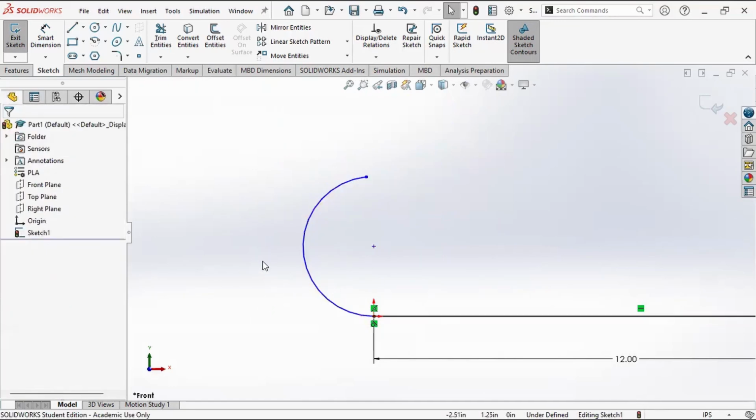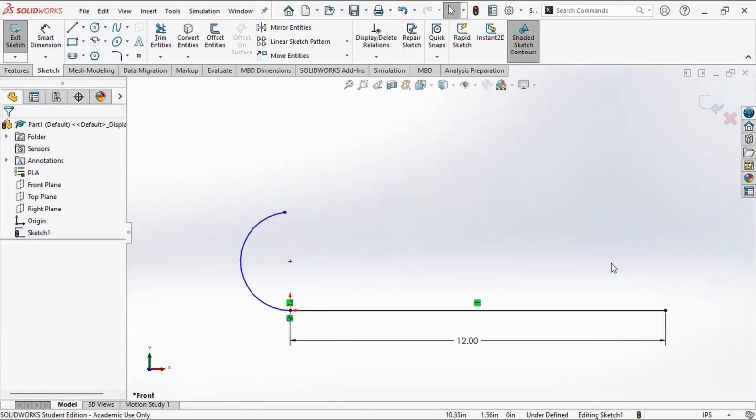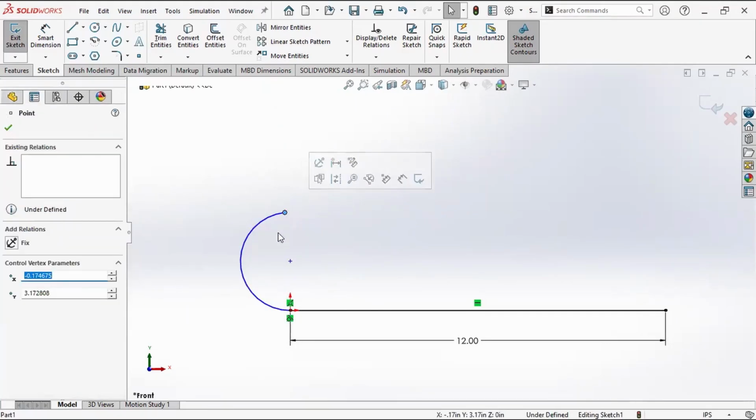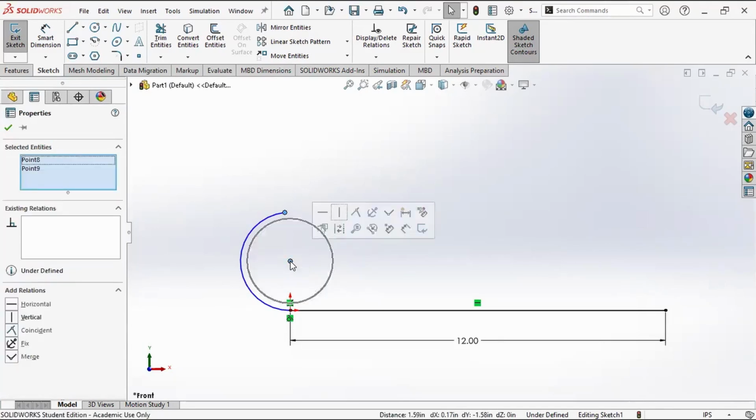So there are a lot of examples that I could go through here with how to define an arc. I will say one of the more common constraints is a vertical constraint. So let's say, for instance, this were the end of a wrench, the back end of a wrench, we want it nice and round so that we don't stab anybody. I would select the top point, the center point, and I'm again doing that by control clicking, and 0. And I can constrain those all to be vertical.